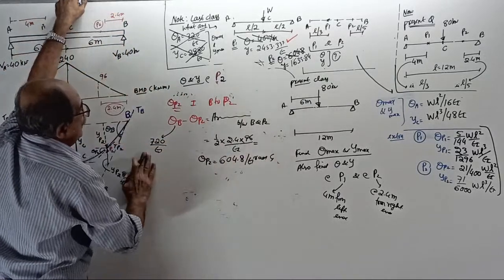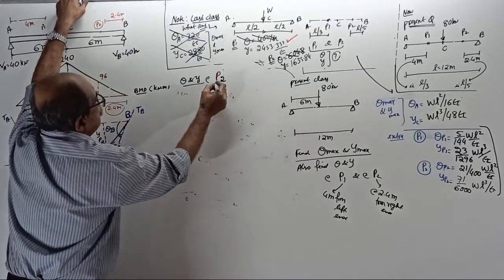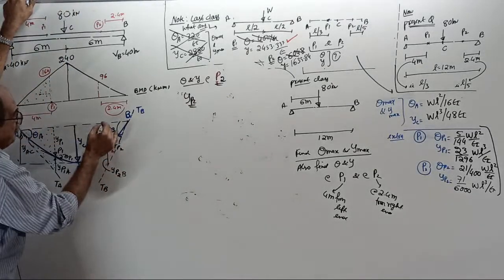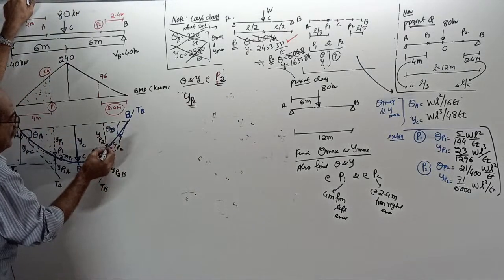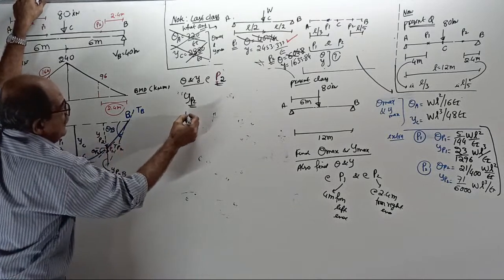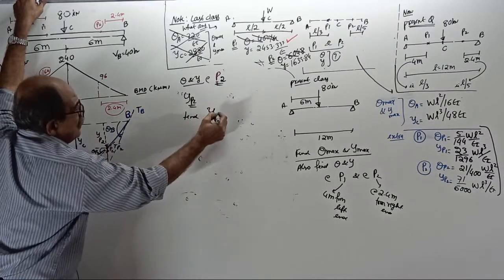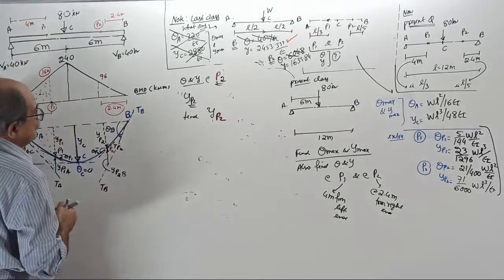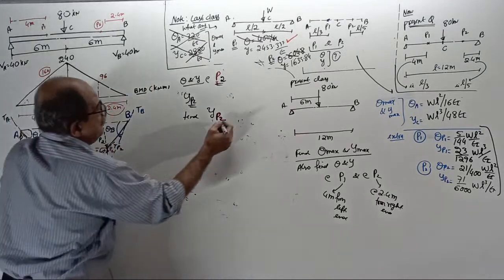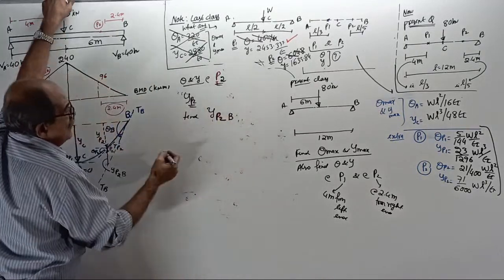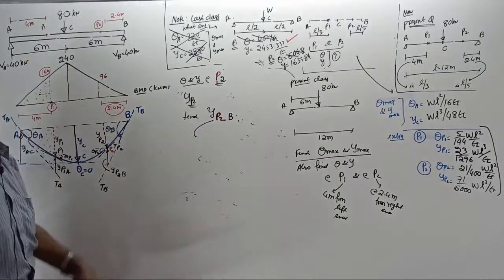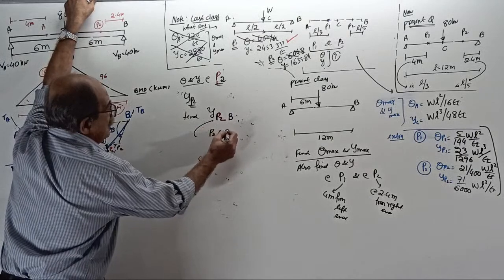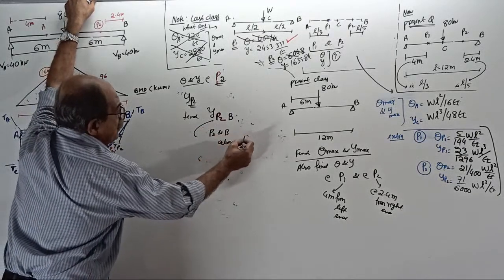Lastly, the closing part: deflection at P2. You cannot find deflection at P2 directly. What you do is find the displacement of P2, that red point, with respect to the tangent at B. It equals the moment of the area of the BM by EI diagram between P2 and B, very important, about P2.